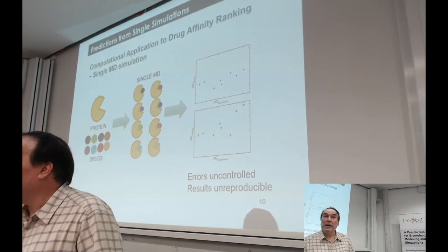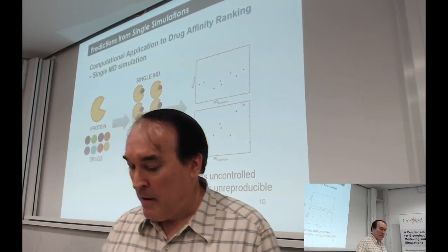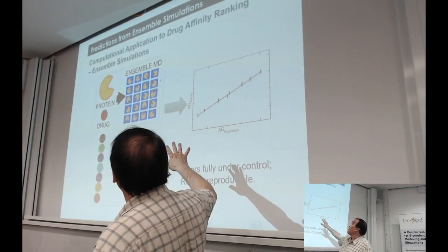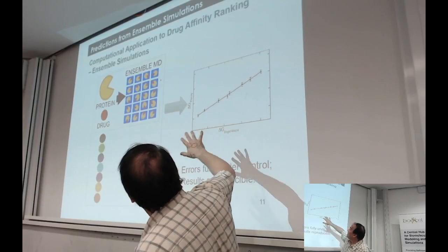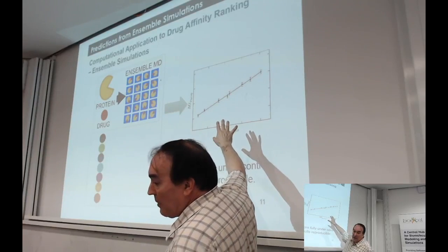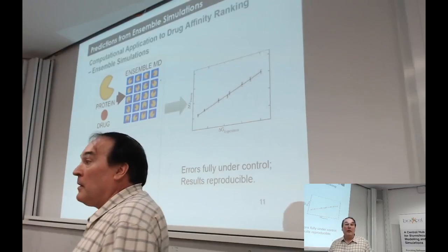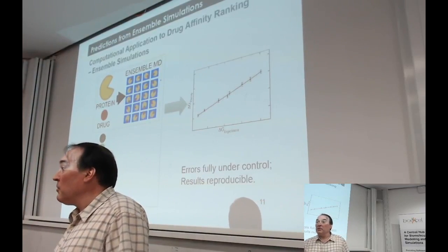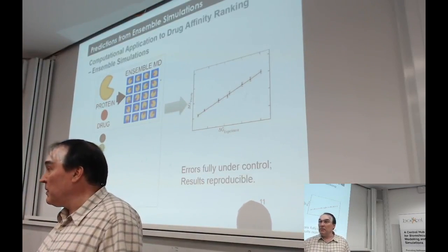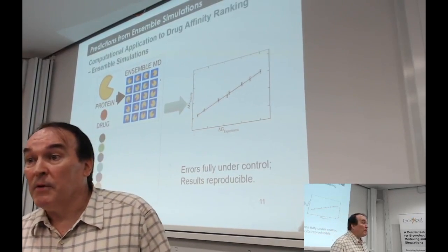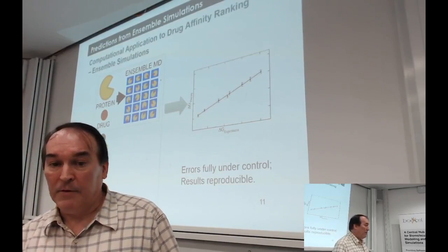And that's where we find what the numbers are that are necessary here. Typically, I'll just take you through what those numbers are, but if you do it nicely and it works out, you can get error bars of this sort. It's really similar to weather forecasting. The systems are different only in that we're solving Navier-Stokes equations, which are dissipative. In weather forecasting, they're conservative dynamical systems. They still have the same chaotic properties.